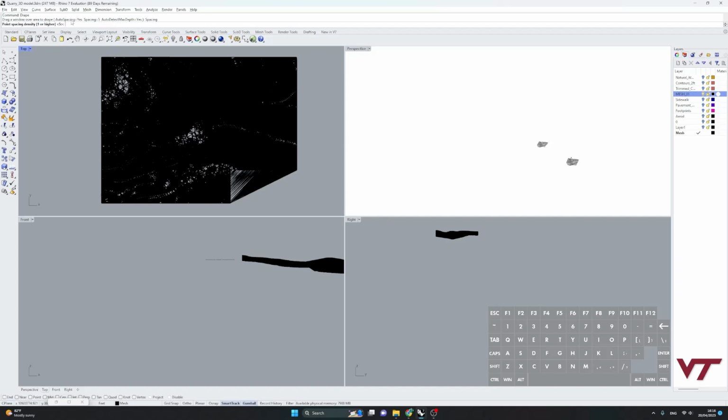Within the commands up in here, when you open up a drape command, we see we have these options. If you click on the spacing one, it's asking us for the point density here. So 1 is high density, I believe. Could be mistaken, but we're about to find out. So let's just drop that across there. Yeah, 1 looked like it was much higher density.